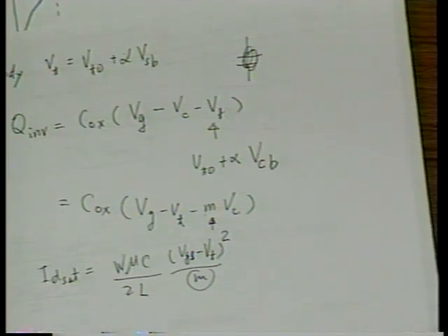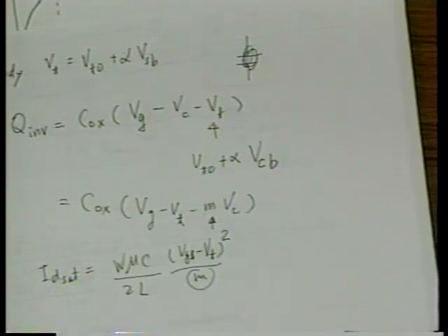So it's for this reason that we have a change in Vt, which also reflects in a reduction in ID, which is commonly called the bulk charge effect. All right? So if you start calling both the body effect, I think it's a very good way of thinking about it. Right?